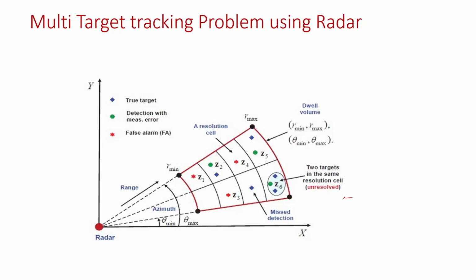Okay. Now, suppose sometimes, though both targets are moving, when they are closely spaced the sensor gives me one, and whenever they are beyond your sensor resolution, suppose in this scan this distance is more, now the sensor can give me two, and it keeps alternating like this. But there is a possibility that if my algorithms are incorrect, I will give only one target and fail to resolve. So, my tracking accuracy will need to be improved. Okay. This is a very important fundamental in tracking.